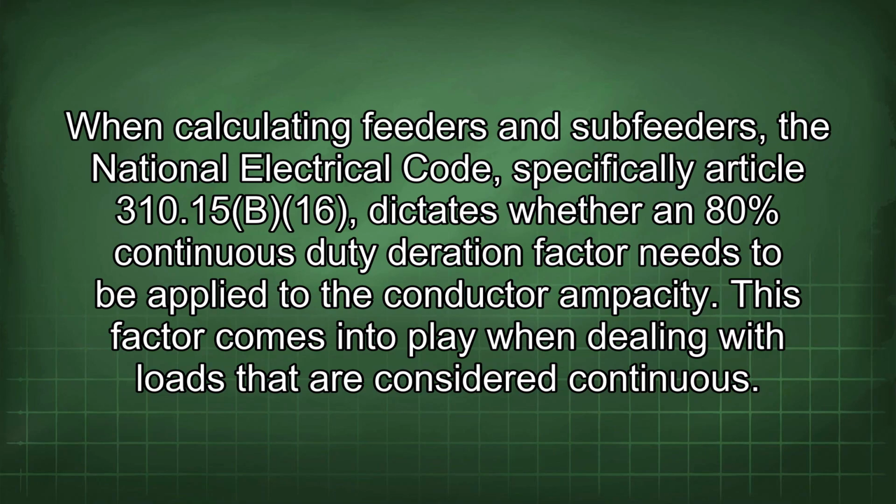When calculating feeders and subfeeders, the National Electrical Code, specifically Article 310.15(B)(16), dictates whether an 80% continuous duty duration factor needs to be applied to the conductor ampacity. This factor comes into play when dealing with loads that are considered continuous.